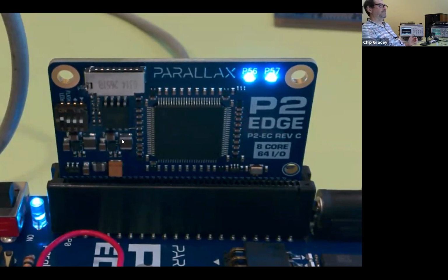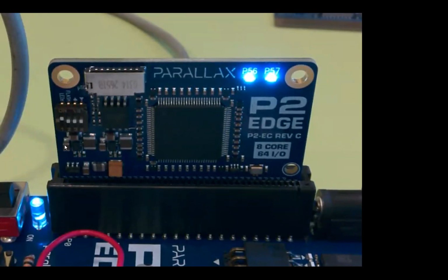I think for an automotive app, you'd want to put something in front of this for power. You just need a little circuit with about six components to do the protection. Because one single diode is not able to drop enough. Two diodes in series will be enough to limit, and also some absorbers. Perfect.